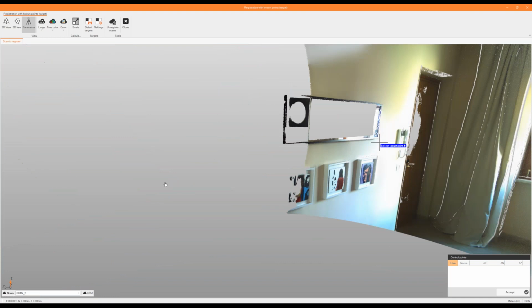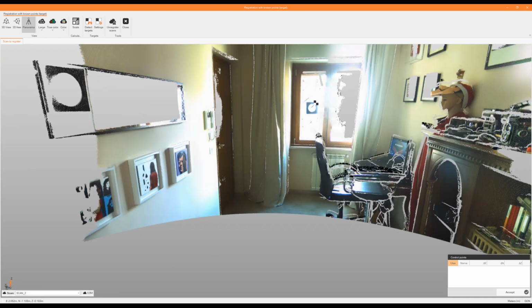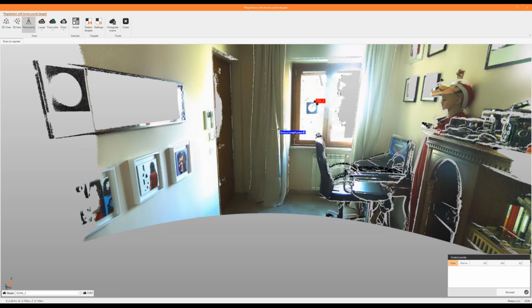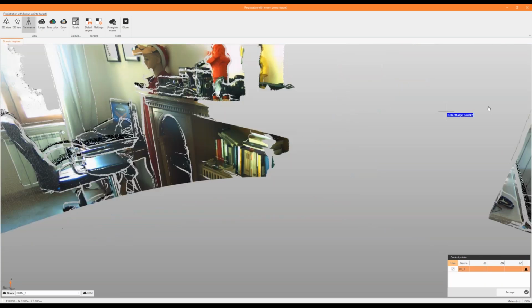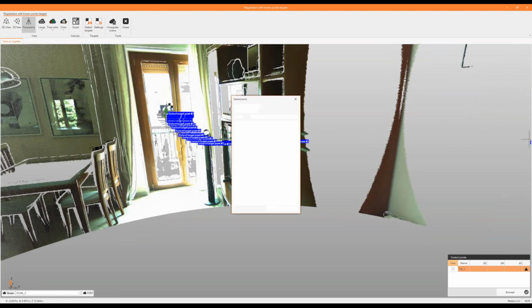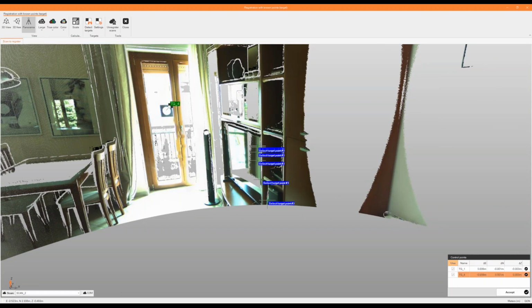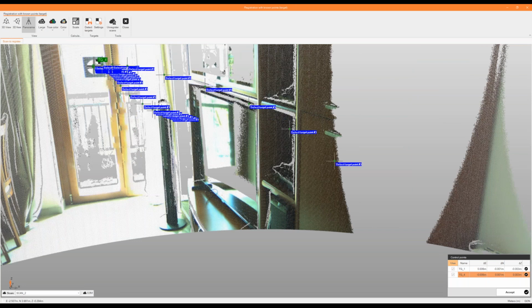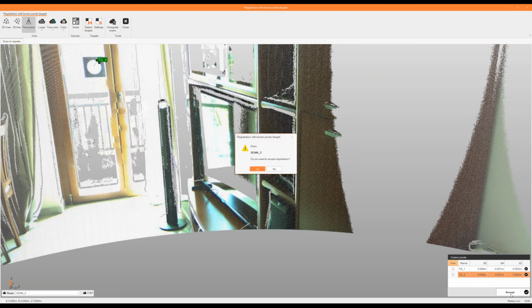a good position. So in that case, we will use, for example, target 1. I already imported the TPS data. And this is the target 4. Here we can also check the deltas of the 3 different coordinates. And once we have good accuracy, as you can see, we have the automatic snap on the target. We can update this registration.